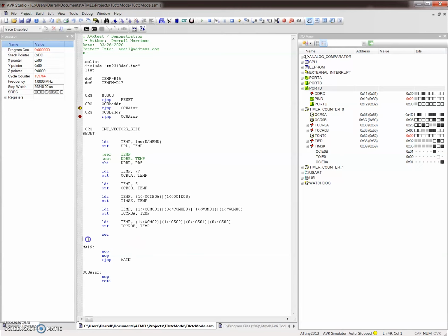But before we do that, I think it would probably be a good idea to go to timer 1 and do that, because we have such low resolution on here. We don't have very much control, and it's probably not very usable for a servo motor, because it'll be really glitchy. One push of the button and it's going to jump several degrees. So it'd be better to go, and we'll do another video at a different point in time while we're using timer 1, and we'll do the PWM. Using timer 1, we'll have much higher resolution.